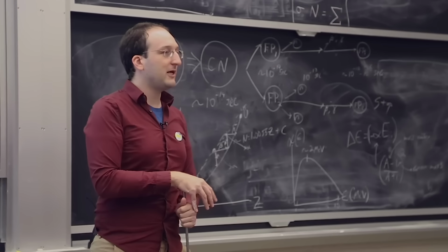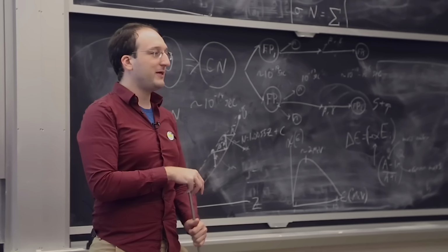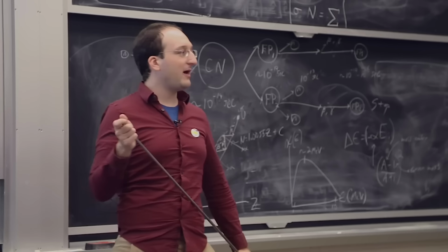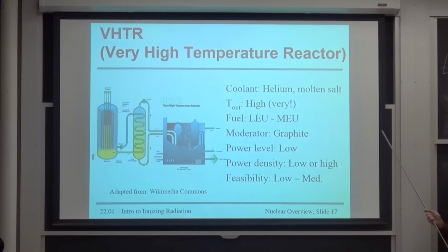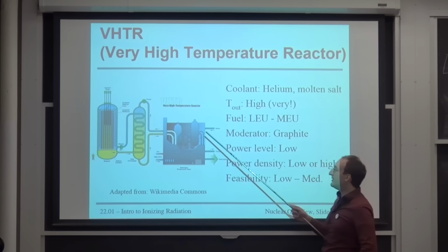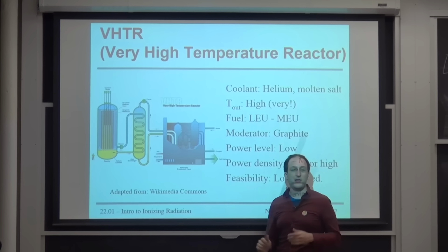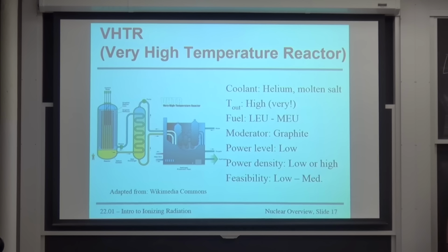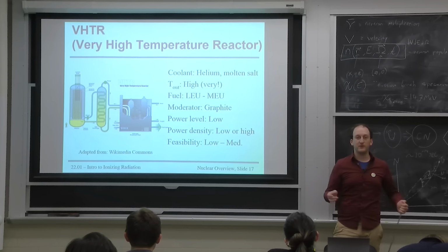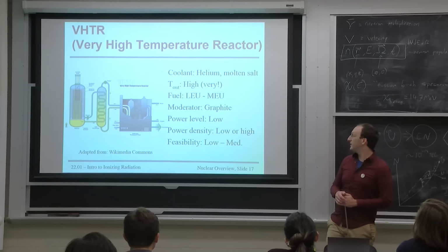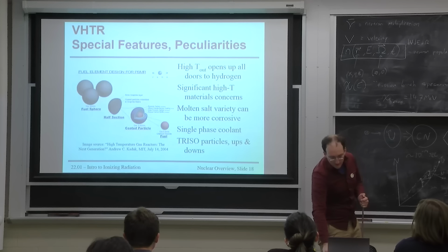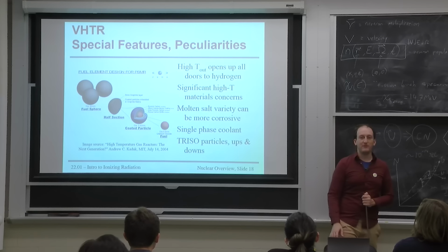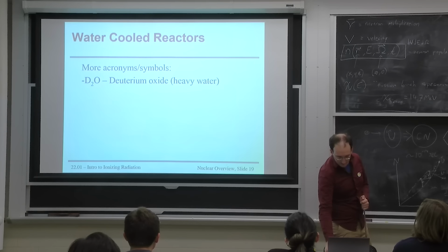It's not the helium itself, but the impurities in the helium that could really mess you up. And the sorts of alloys that they need to get this working, these nickel superalloys like alloy 230, they can slightly carburize or decarburize depending on the amount of carbon in the helium coolant. Either way you go, you lose the strength that you need. So I'll say feasibility is low to medium because, well, we haven't really seen one of these yet.